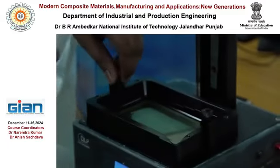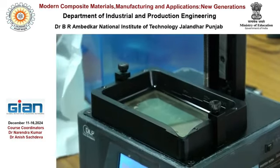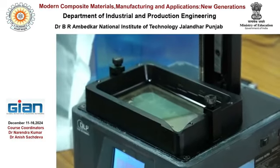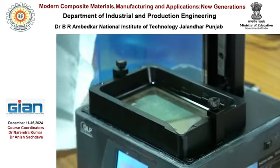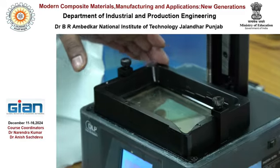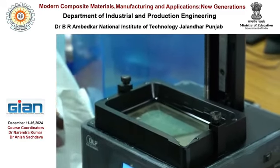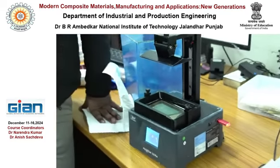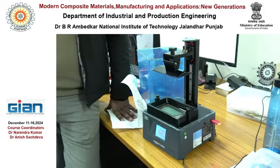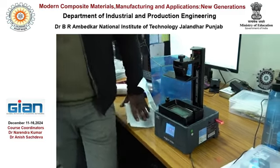So this is the vat. We can remove it from here, just to clean the vat. If we have to change the material, we need to clean the vat also. So we can remove that vat from here with these screws. We have to wash that vat with the chemical that we have.